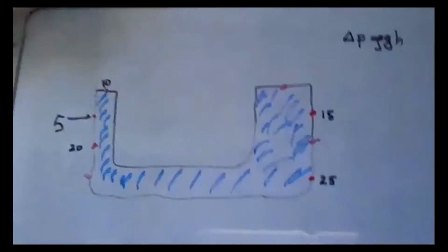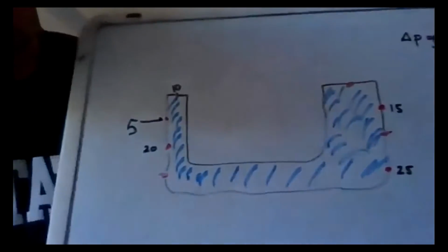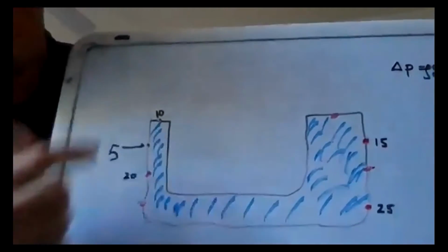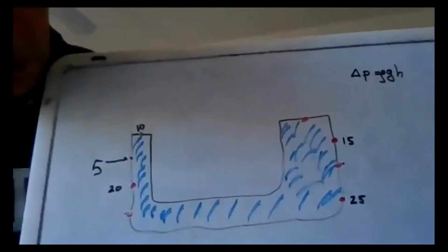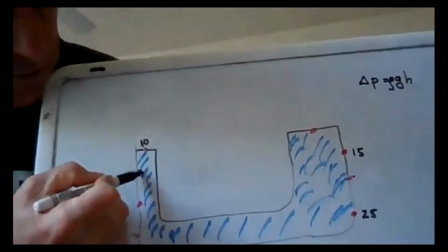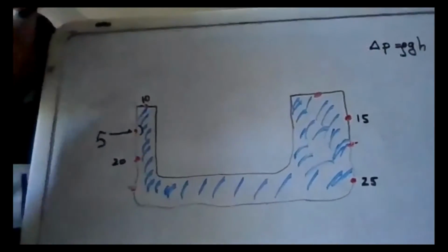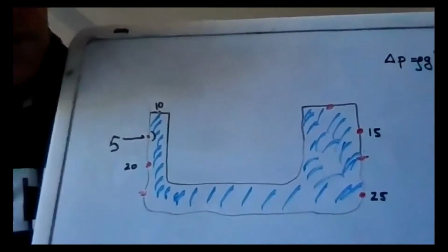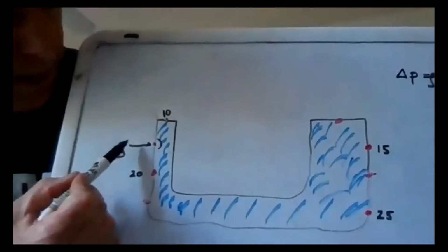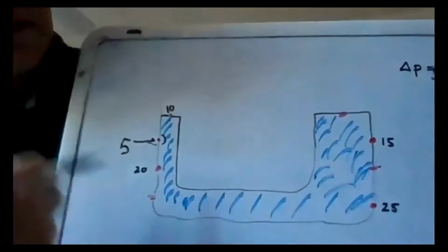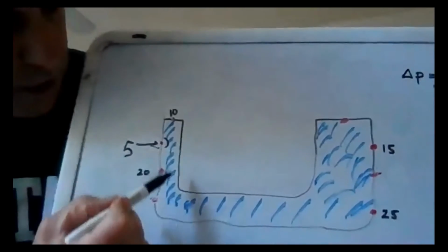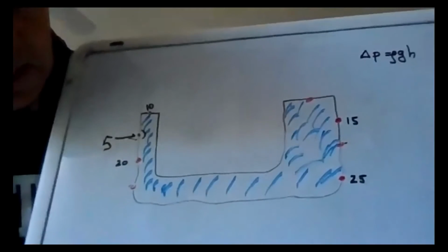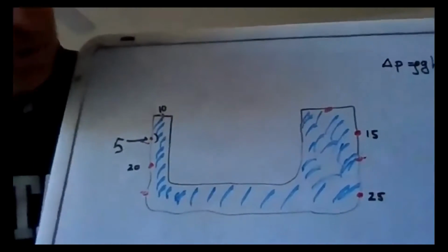Well, hopefully your intuition's good, but let's just go through it really quickly. First of all, this pressure that's added, maybe something's pushing right there, it is creating a compression, okay? It is creating a compression there like that. And that compression is going to travel through the fluid at what speed? Well, at the speed of sound in a fluid. And for purposes of a lot of devices that use applied pressure to a fluid, that's virtually instantaneous. So this compression is going to travel and spread through the fluid and make it over here almost instantaneously, as long as this enclosure is not huge.